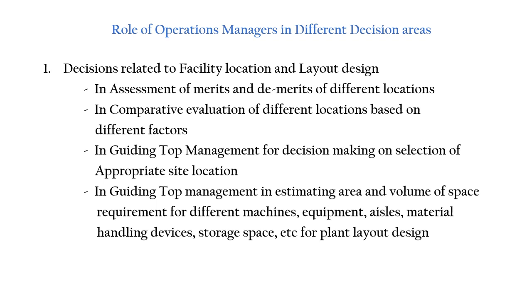So the space requirement, that is area as well as volume for different machinery, equipment, and the aisles to be provided between the facilities to facilitate the movement of men, material, or for other transport purposes, internal transportation.